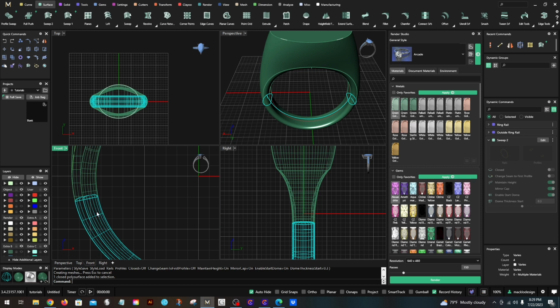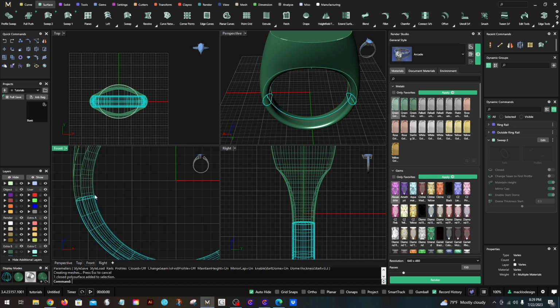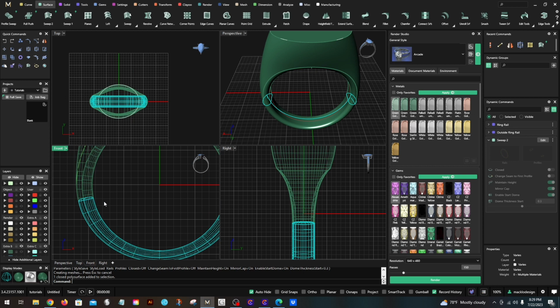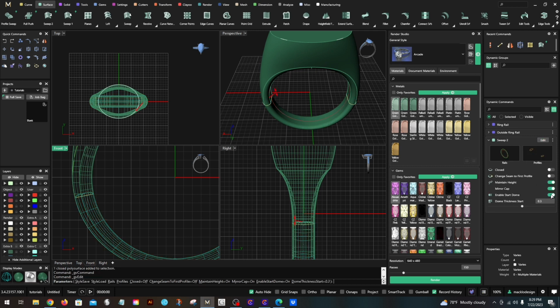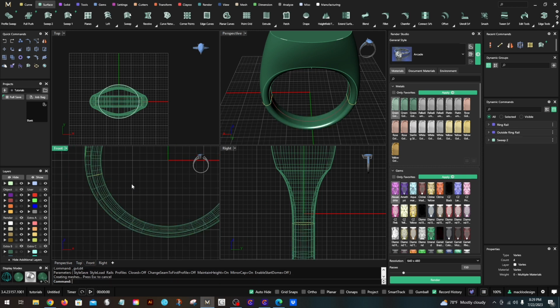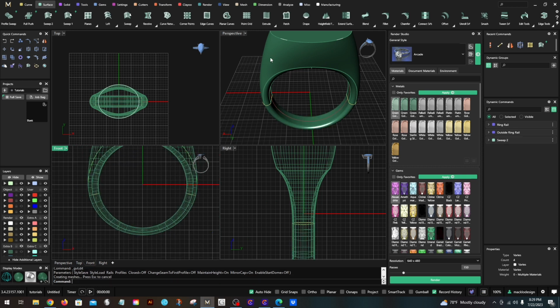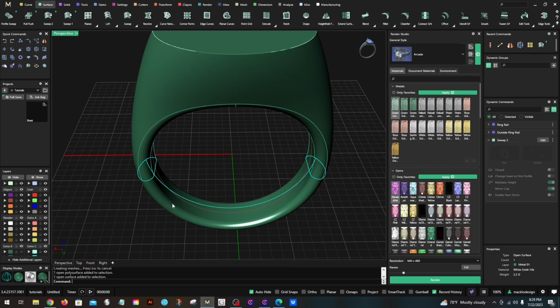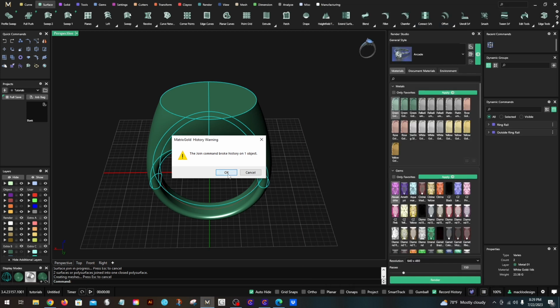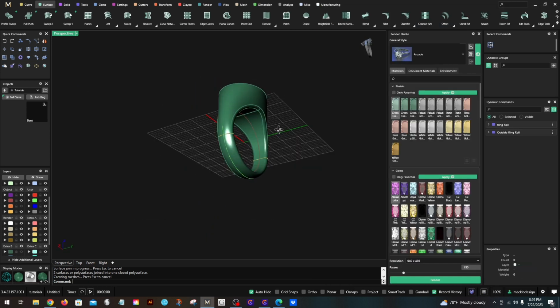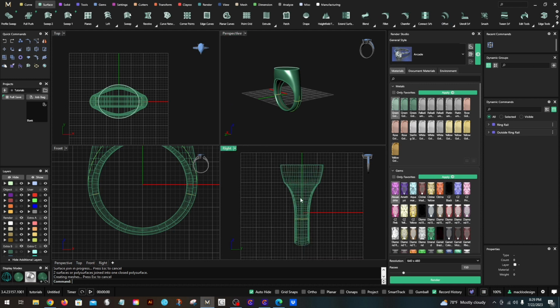Okay, so I made a mistake here, and I did not click off the toggle in the dynamic command box. So I'm going to select that and go over here to sweep to edit, and I'm going to click that off so that there is no cap, because I do not want a cap on that, because this has no cap and this has no cap. So now I can select those two and join them using the quick command. Okay, very nice. That's looking very good.